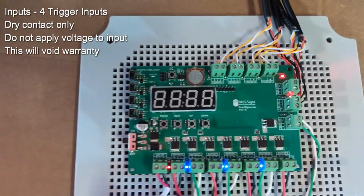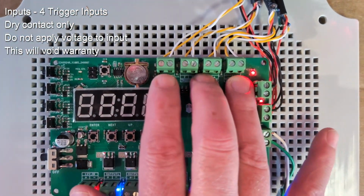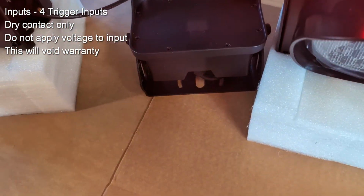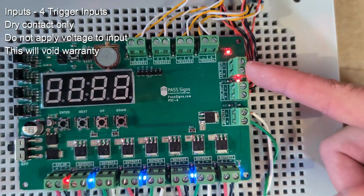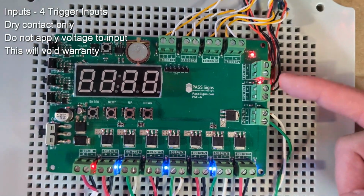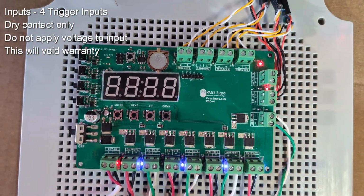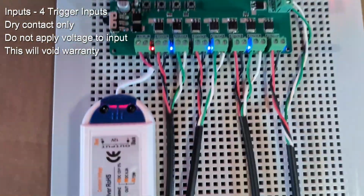Inputs. So there's 4 trigger inputs located on the board. Input 1, 2, 3, and 4. The power for your sensors, such as these motion detectors here, can come directly from the board itself. You don't have to put it in an extra power supply. This will output 12 volts DC for power for your sensors.